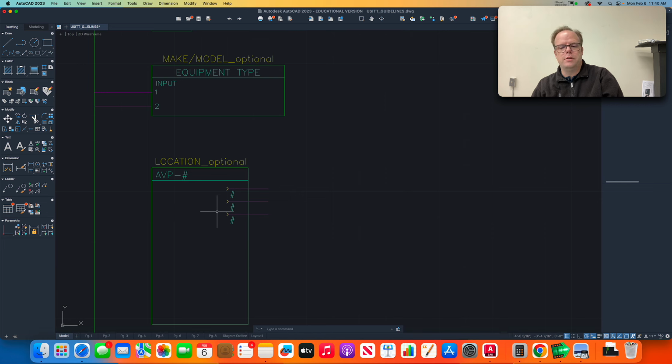You can, while you're in the middle of the command, go over and turn it off. Okay, but if there is a shortcut, I don't know what it is. I've never learned that. But yeah, sometimes the snapping gets in your way. Yeah, it was just in my way. I know Vectorworks is hold this. I'm not sure, but I always, if I ever need to do that, just go down and click it off for that command, and then it usually comes back on after that command.